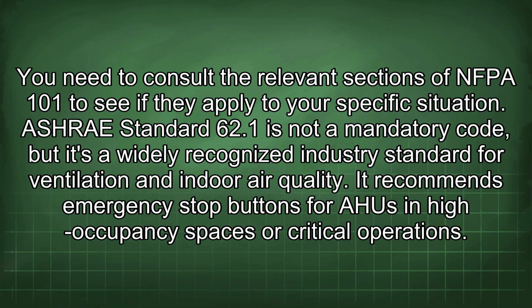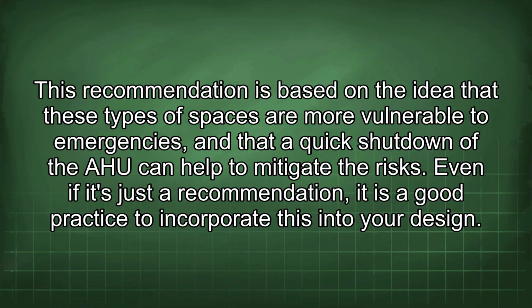AHU Standard 62.1 is not a mandatory code, but it's a widely recognized industry standard for ventilation and indoor air quality. It recommends emergency stop buttons for AHU in high occupancy spaces or critical operations. This recommendation is based on the idea that these types of spaces are more vulnerable to emergencies and that a quick shutdown of the AHU can help to mitigate the risks. Even if it's just a recommendation, it is a good practice to incorporate this into your design.